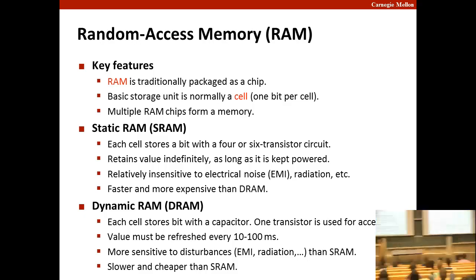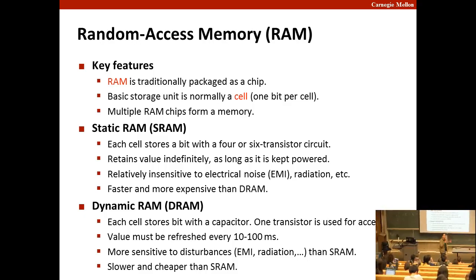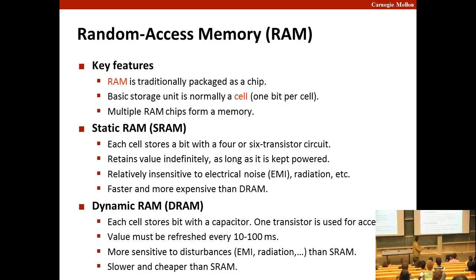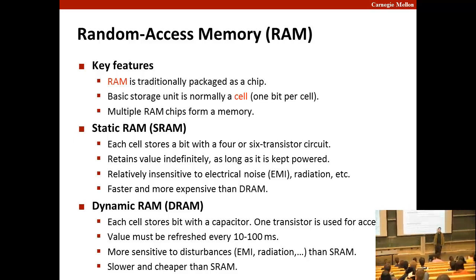Now, if we look at our system's main memory, it's composed of something called DRAM, or dynamic RAM. Dynamic RAM basically stores values, ones or zeros, in a capacitor, meaning as stored charge. The problem with DRAM, or one problem with DRAM, is the stored charge leaks out over time, and so it needs to be refreshed.